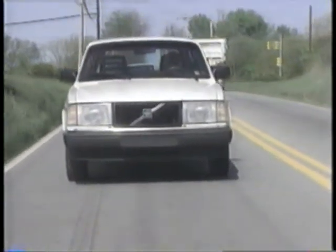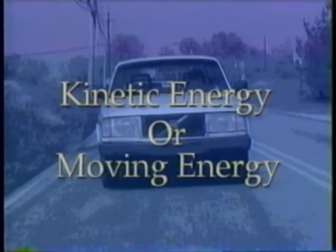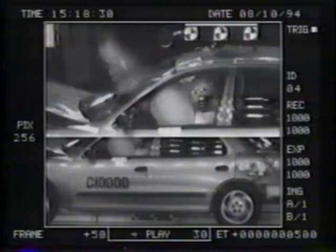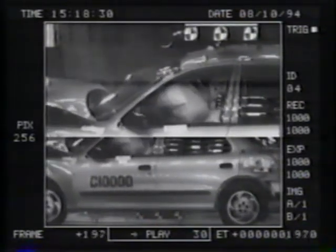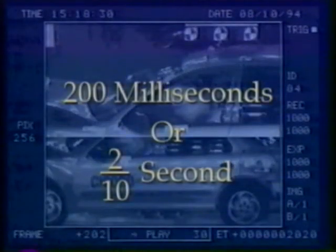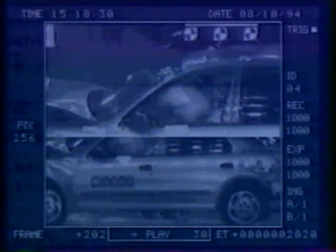In a moving vehicle, it must be remembered that the occupants are traveling at the same speed as the vehicle. The moving vehicle and its occupants represent kinetic or moving energy. In a crash, things happen very quickly. The total time from the point a vehicle contacts an object and begins to decelerate until the vehicle stops moving and the damage to it is completed occurs in approximately 200 milliseconds, or 0.2 of 1 second. In about half that time, or 1/10 of a second, the occupants will come to a halt.